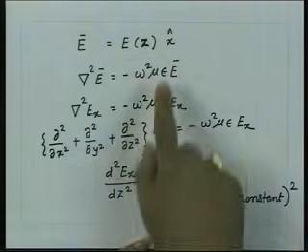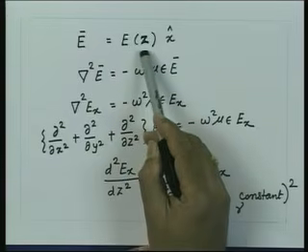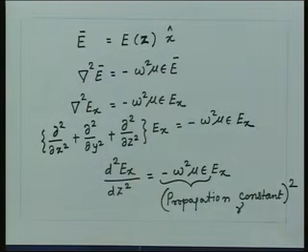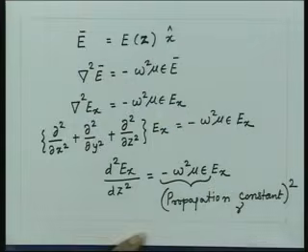In the previous lecture we started discussing the solution of Maxwell's equations in an unbound medium. We saw that the simplest solution which can exist in an unbound medium is an electric field which is constant in a plane containing the field vector and has a variation perpendicular to the vector. So, without losing generality, we had considered electric fields which were x oriented and had a variation only as a function of z. That means we assume that the electric field was constant in the xy plane.